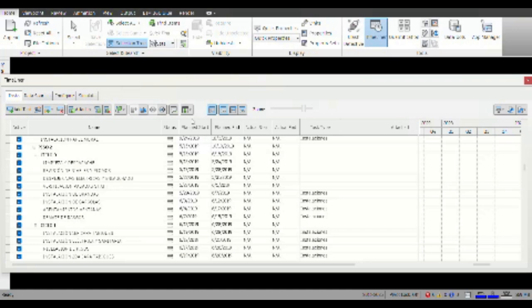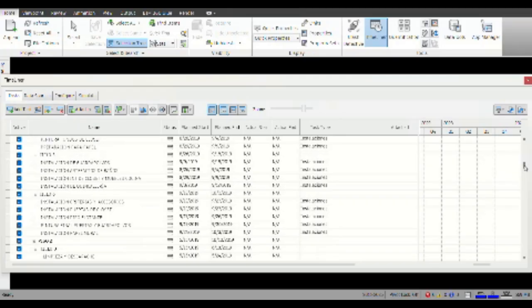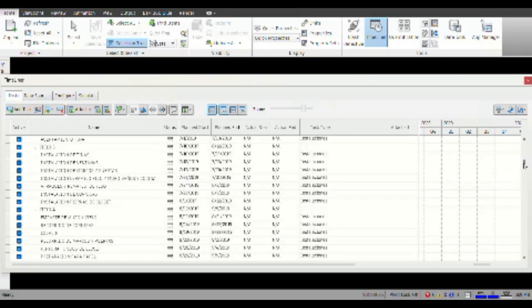The dates on this stage reflect the typical timeline of a construction project. Rebar installation takes 4 days, and depending on the section, formwork follows with a similar duration. Concrete pouring lasts 7 days, considering the amount of material needed as well as the time required to start working on the next elevation. And the average duration between each floor is about one month, or a month and a half.